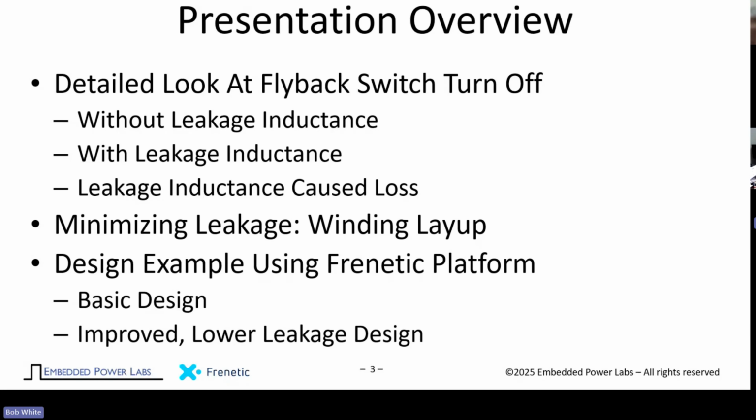We're going to take a very detailed look at what happens when you transition from the on time, when the switch is on, to the reset or demagnetization time. I'll start by doing that without the leakage inductance, just to get oriented. And then with the leakage inductance, things get more complicated. Then understanding the loss and the calculation. There are some circuit design techniques I'll briefly discuss to minimize that loss.